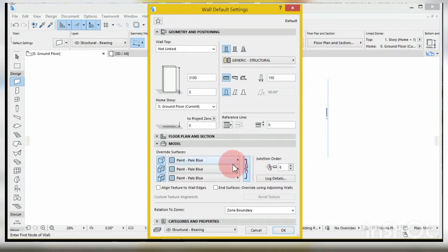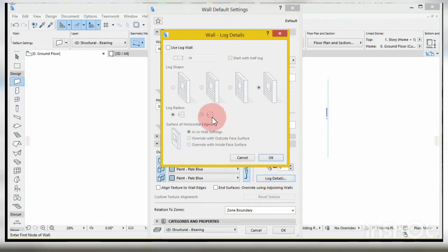So next place I will do, if I want to have a wall log on my wall, I can click on this, and then you see use wall log. That is the line, the horizontal lining on the wall. So that's what I mean by this wall log. You can see most designs do have this. So I remember my wall line is not supposed to exceed the overall height of the wall, which was 3,100 mm that I chose. So let's say I use 900.